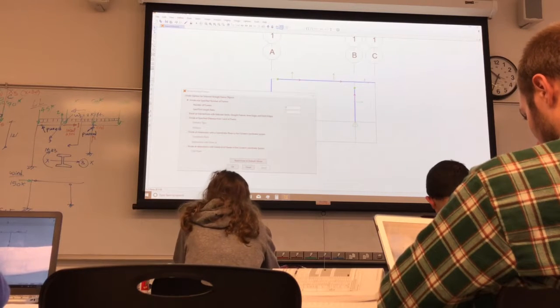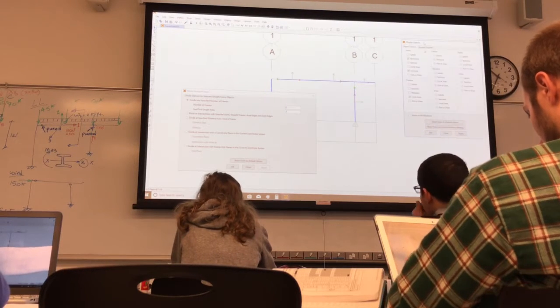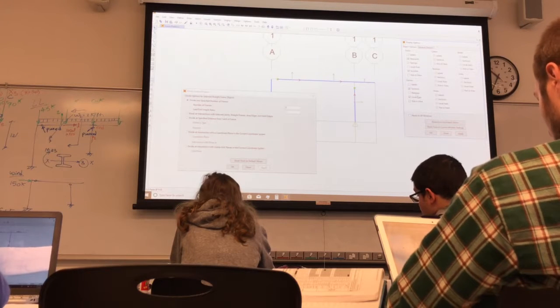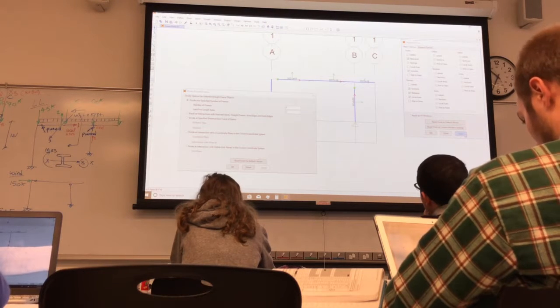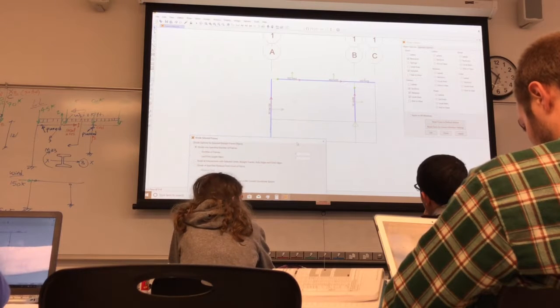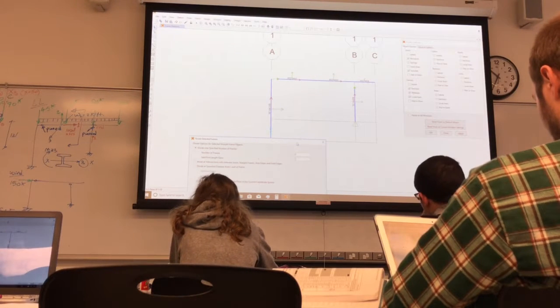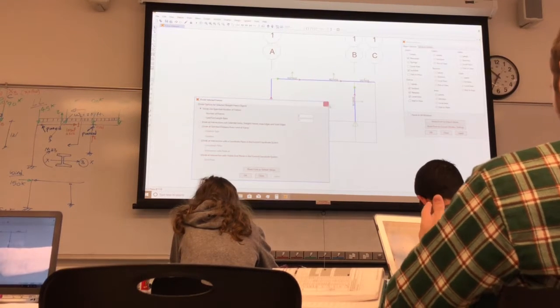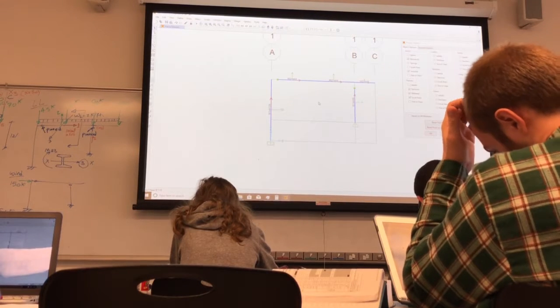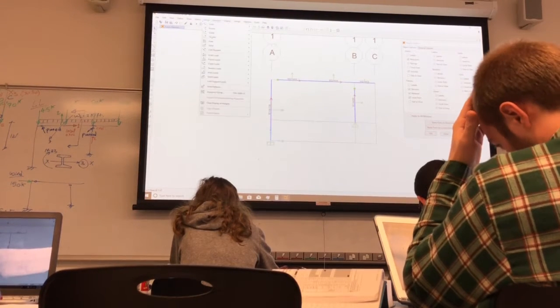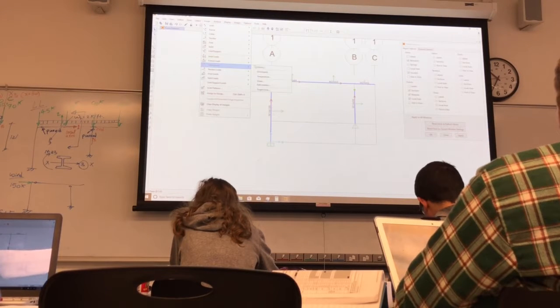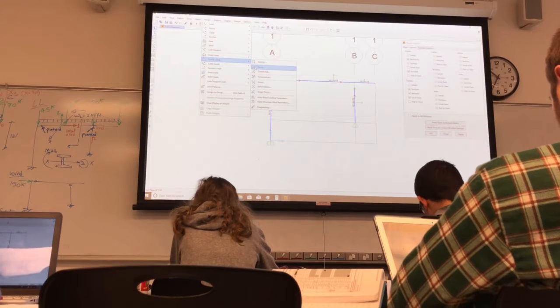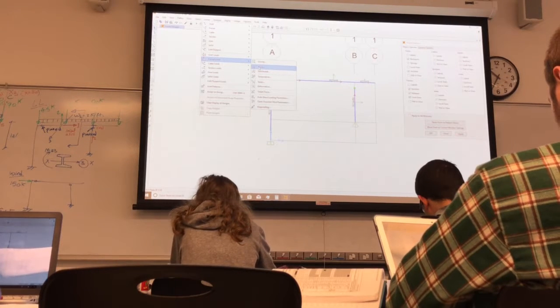And you can go back, you see you have this option that shows you the sections, releases, local axes, everything you need, so it still works. So now I put a node, I split it, and that doesn't affect anything. It just makes it easier for me to apply point loads. You don't have to use that option, because there's another option where you can apply frame point loads, but you have to measure distances, which becomes complicated. It's just easier to select joints.